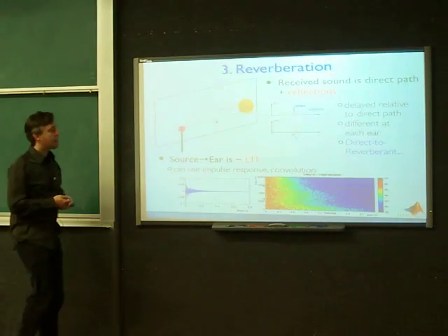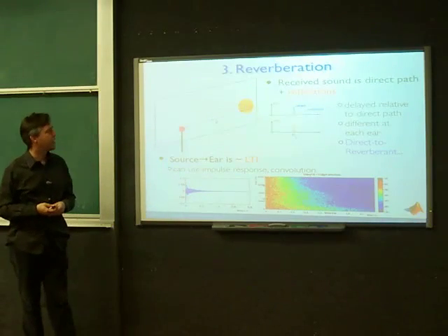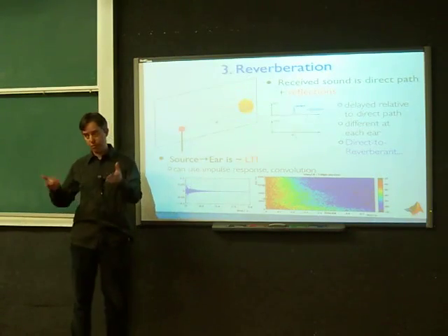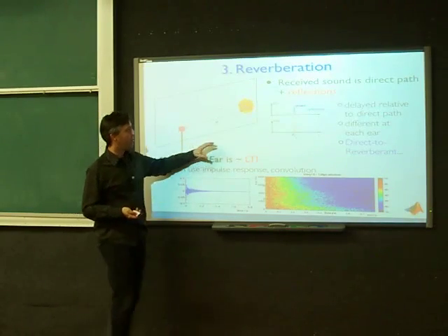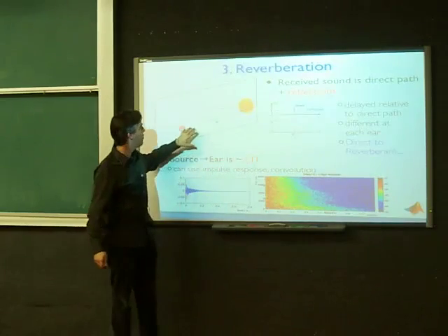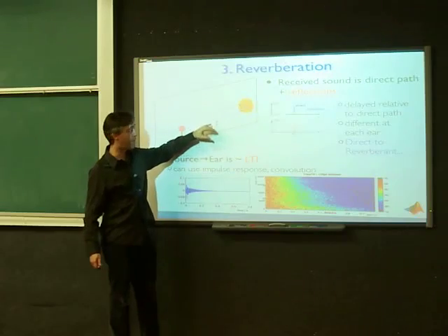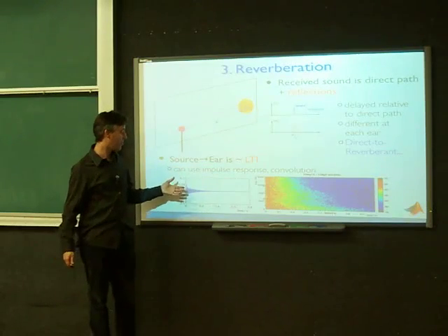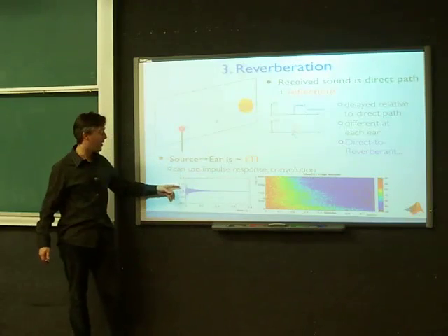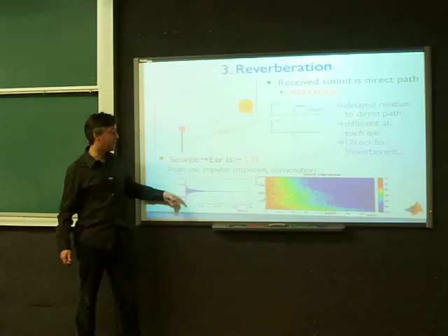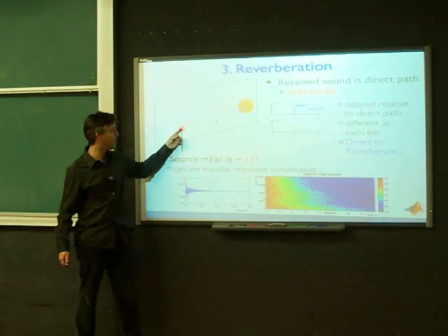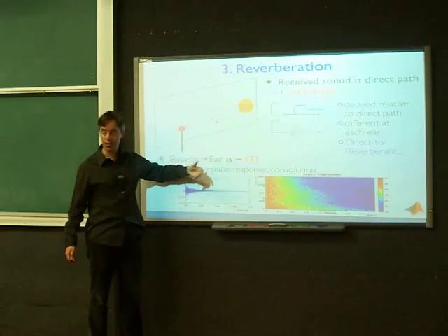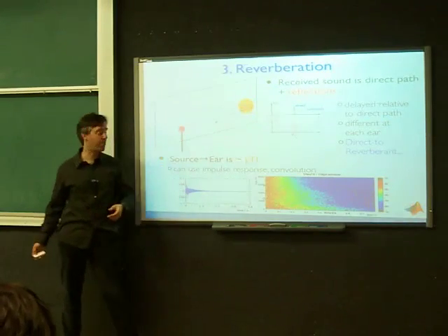Okay, so the last thing I wanted to introduce was reverberation. And reverberation is what we experience in rooms, and you can characterize it as an impulse response. You can model it as a combination of direct and reflected paths, which you can then describe as impulse responses, and you can generate this by simply building the impulse response or sampling it and then convolving it with the source signal, because this is exactly what's happening when you have a single source and some receivers out here going through a channel which has reflections. It's just convolution. Whatever impulse comes out of here gets put through these reflections.